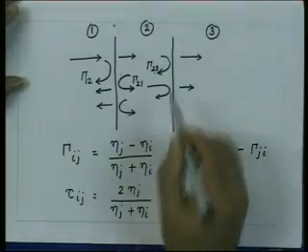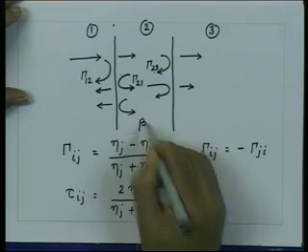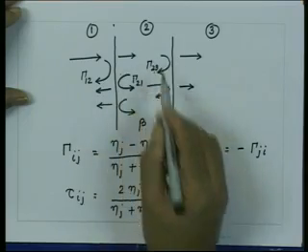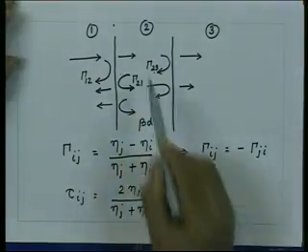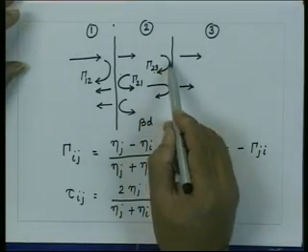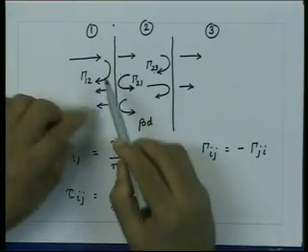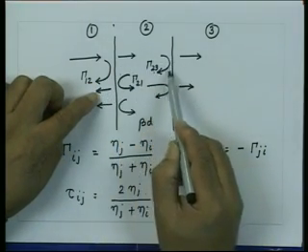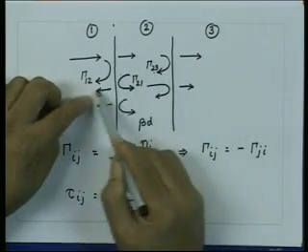So, now if I write down, and you are having this distance d, and the phase constant in this medium let us say is given by beta. So, you are having the phase change when the wave travels from here to here, which corresponds to beta d. So, this wave travels a distance with phase beta d. When it comes here, it has traveled a phase which is 2 times beta d. So, now what we have here is the first reflection plus the second quantity here, which is 1 reflection here, 1 transmission, 1 reflection, and 1 transmission, this way.